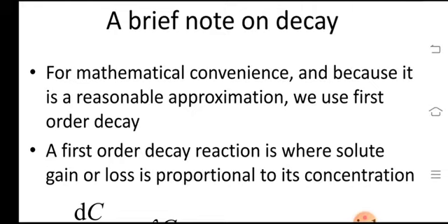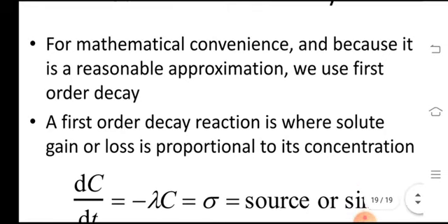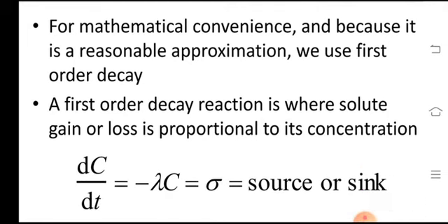For example, chromium in fresh waters is hexavalent chromium. With the passage of time, this hexavalent chromium gets reduced to trivalent chromium. This trivalent chromium has more affinity to get attached to the solid particle, that is, clay. Because of this attachment, the trivalent chromium is more easily available in the solid particle than in the aqueous phase.